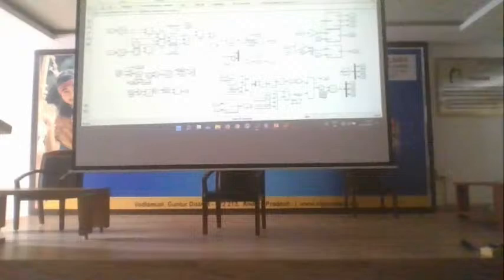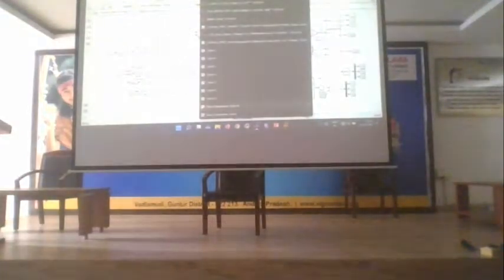That is what happens. In discharging, you see that this is positive and this is also positive. You can see that both are coinciding with each other. This blue is at peak here and your current is also at peak. This is how we are able to maintain the quality of power in the sinusoidal current. Typically, you will not get it like this if you are not applying proper control. So the current is no longer non-sinusoidal like this. Right. So you are achieving unity power factor and good quality of power.